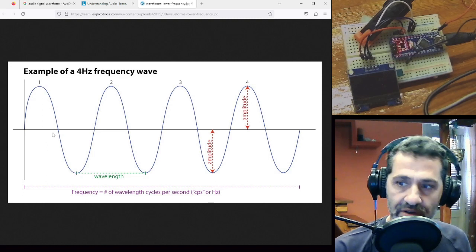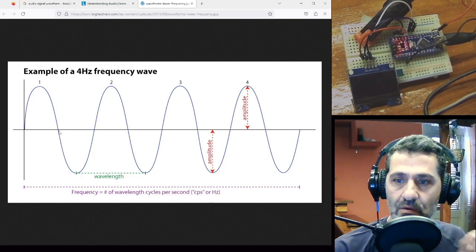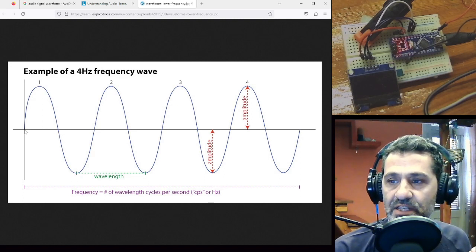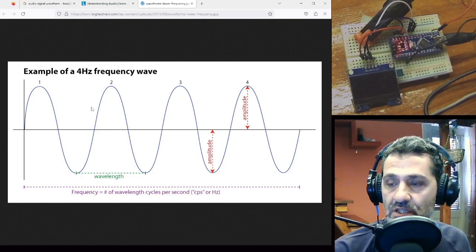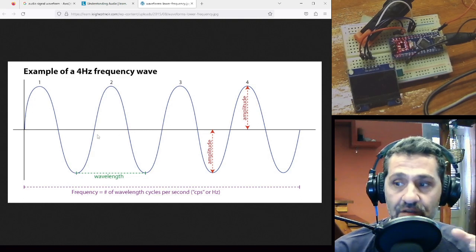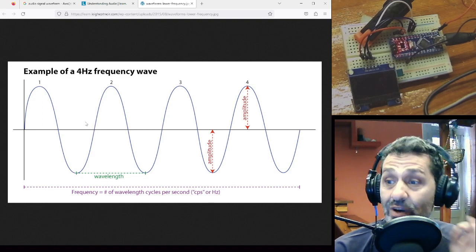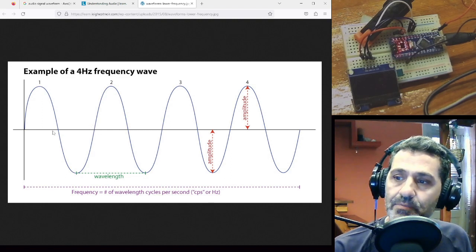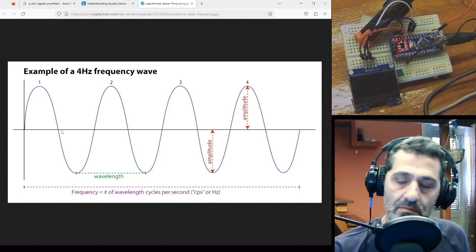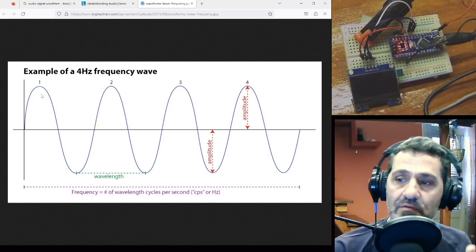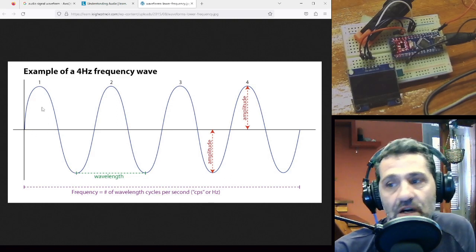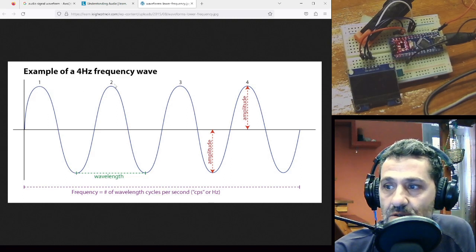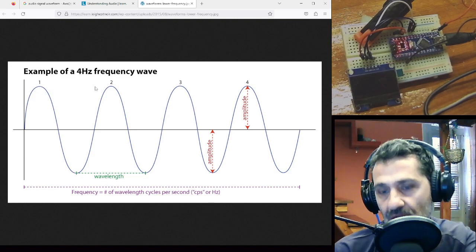There is a way to get over this, and I will show you which will be the way. The way will be that we get a series of random inputs, for example, from here to here. Okay, it will be one here, here, here, wherever it will be. But we will take as our value the maximum value of all this, hoping that some of the values will be around here or around here, which is the amplitude of the signal.